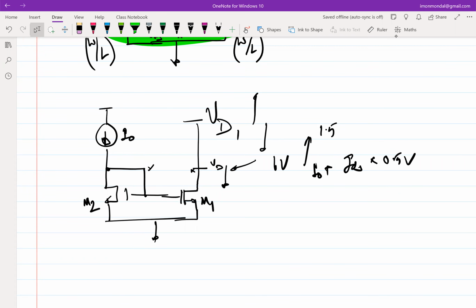So it basically boils down to what you are trying to use that for. It boils down to error accumulation, right? You are getting an error term by one method, but then you are multiplying it with a bigger term, so your error will increase. So basically, I'm incorporating the error in the M2 part whenever I'm calculating the VGS, and then in the next part I am using the accurate equation. Exactly. That's basically creating the problem.